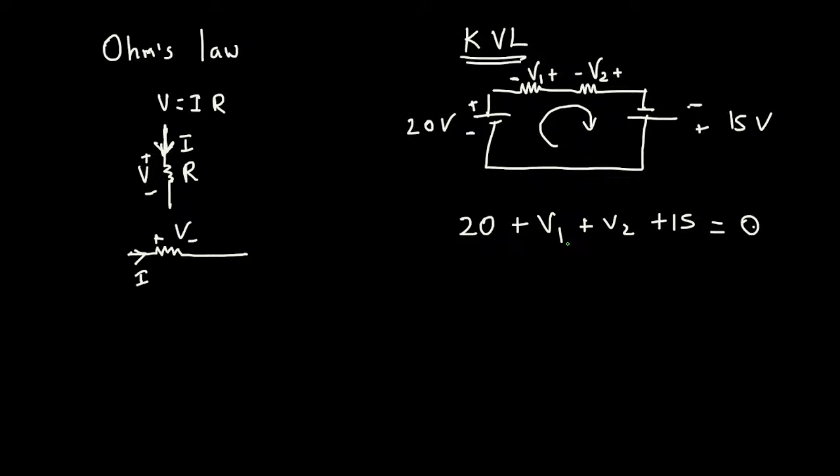Okay, and then let's say if the question is asking us to find out the current, like let's say we are assuming the current to be this direction. You can assume this direction or opposite direction. If the assumption is wrong, we are gonna get the negative answer. So negative means it's in the opposite direction. Actually, it's not this direction, but as long as you mention negative, you don't have to change anything. Negative automatically says opposite direction. So let's try to find out the current for this.